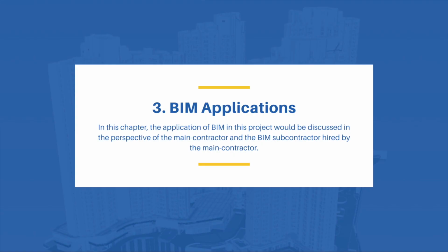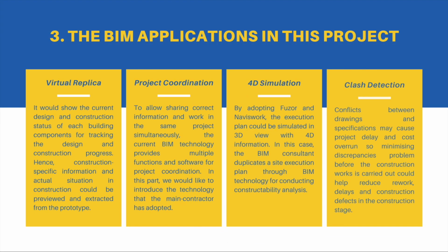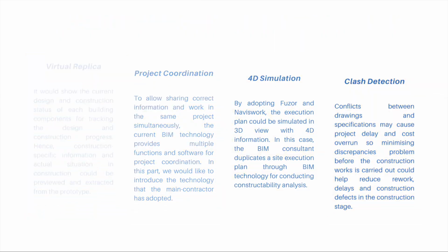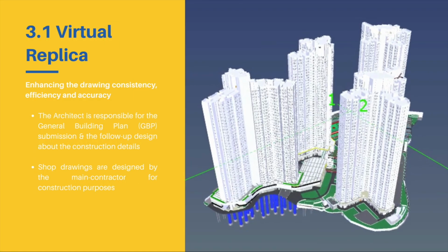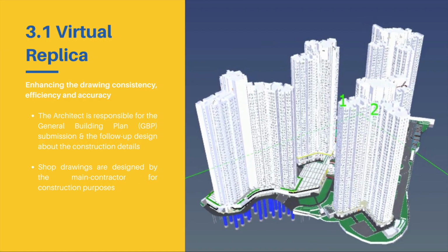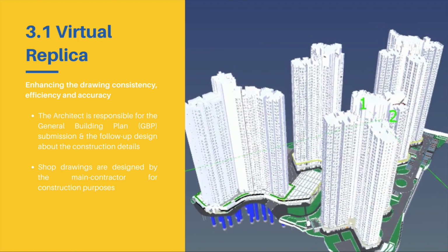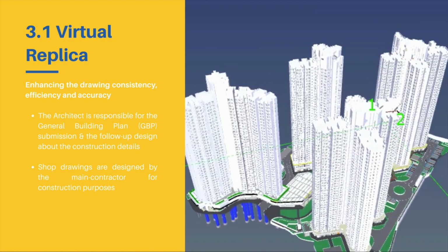In this project, the BIM technology has been applied in different usage, including virtual replica, project coordination, 4D simulation, and clash detection. Firstly, in virtual replica, since the drawings are prepared by different project stakeholders, a reference model could enhance the drawing consistency, efficiency, and accuracy.